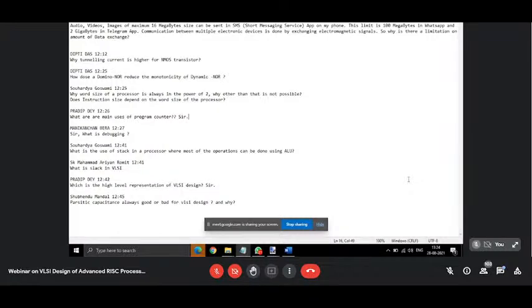For that period, both inputs are 1, so what will be the output? 1, high. For how long? For the gate delay of the NOT gate. Yes, this is a static one error. So this is a problem. This is called hazards, basically. We call it hazards.